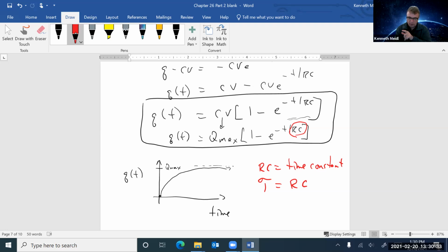So the charge on the plate starts at 0, which we kind of thought, and it builds up to Q max. But it's this exponential, right? And it's a limiting exponential. So it's really building up to that maximum value. So very interesting that something like Kirchhoff's loop rule, just add up the voltage around the loop, gave us enough information to be clever enough to eventually write a separable differential equation, which then leads to this result.